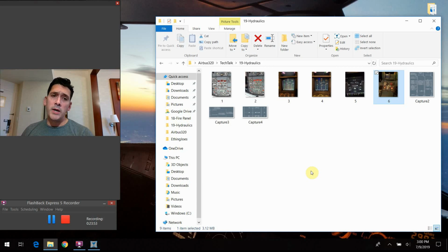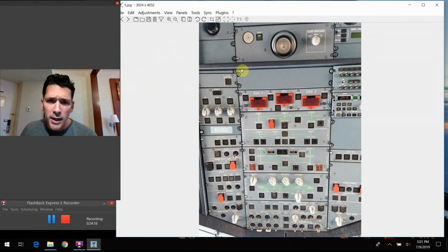So when you push the fire push button switch there, it does a different function. It actually just deactivates or depowers the IDG, or stops it from generating power, essentially. And this is a physically different thing that's happening, as opposed to the scenario when we were using the IDG disconnect switch, the guarded one up on the top of the overhead here.